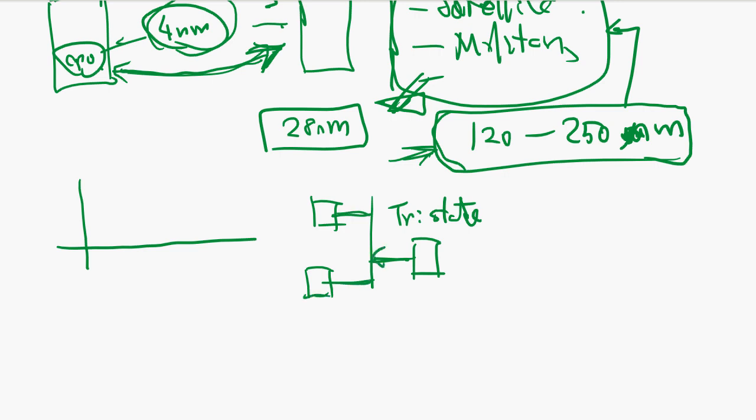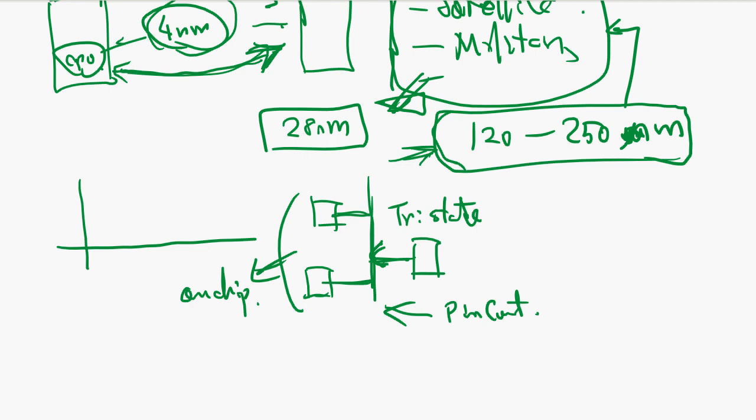Only one using the bus drives the bus, right? And this is not going to be used on chip. The reason why this is used is the pin count. You can't afford to have separate input data and output data pins on these chips, so the data bus is bidirectional.